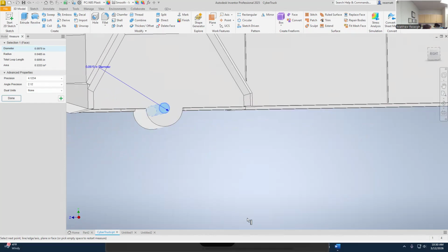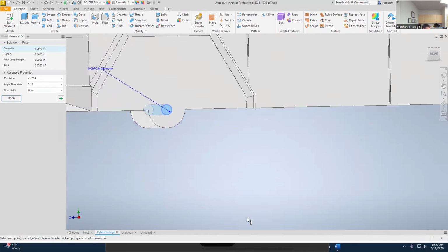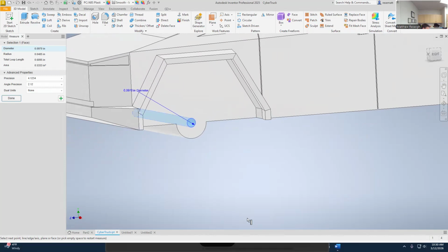I think these worked okay. They were just barely pounded in. Plastic is a little bit like wood. You don't get too many attempts before it becomes a loose axle in that hole, like if you had to pull it in and off. I try not to do that, but I definitely want an interference fit so that as I put it in, I don't have to.